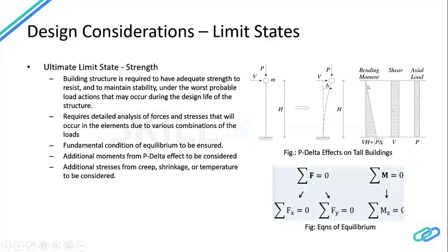And then you will also have bending moment in the building, you will have shear in the building, and you will have axial force in the building. Now, we as a designer will be trying to design a structure which is in equilibrium. So basically, you will have to make sure that your building is able to resist all the forces acting on it.